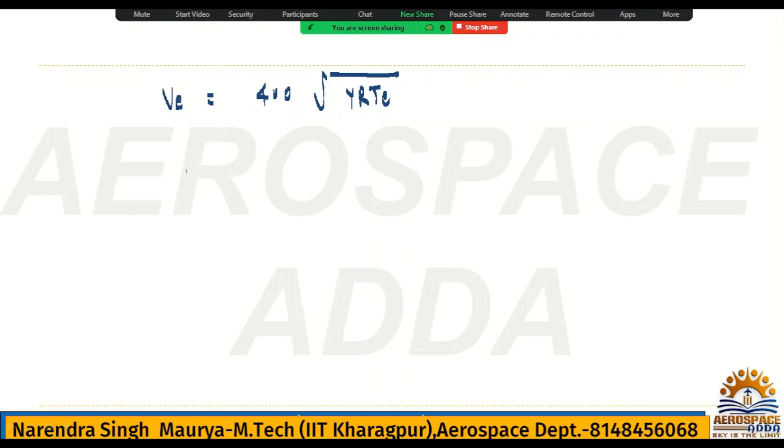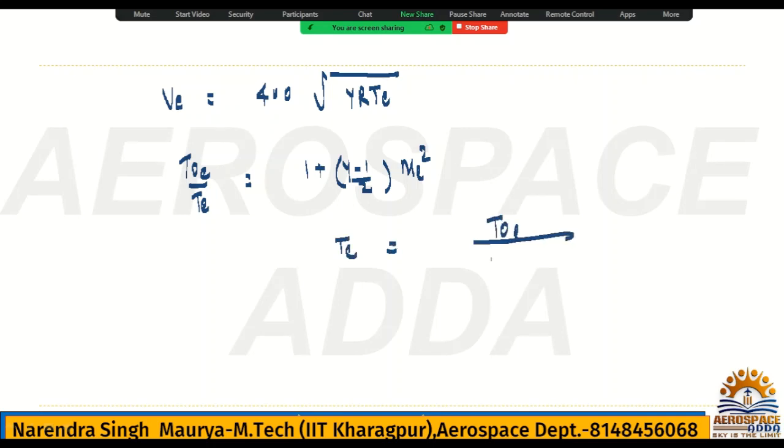What is TE? That formula I have already written for the previous problem. Similarly, I am writing here. This is the isentropic relation at the exit: T naught E by TE equals 1 plus gamma minus 1 by 2 ME square. So TE you can write as T naught E divided by 1 plus gamma minus 1 by 2, ME is nothing but MA, square.